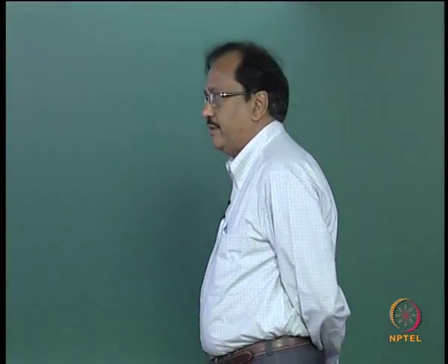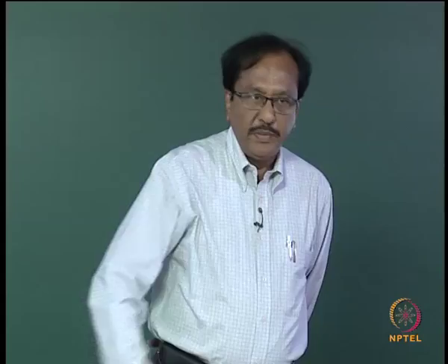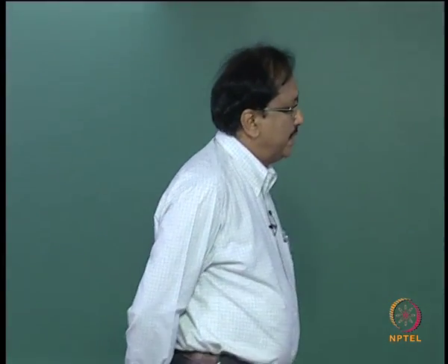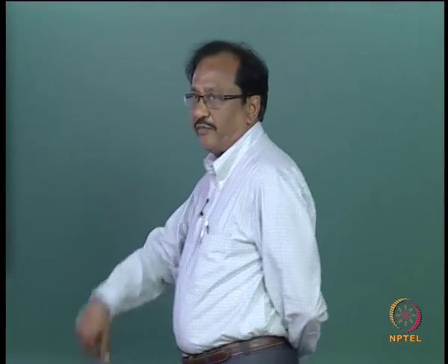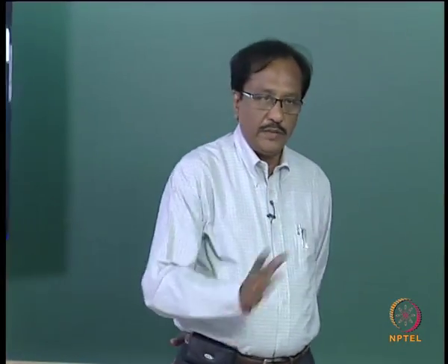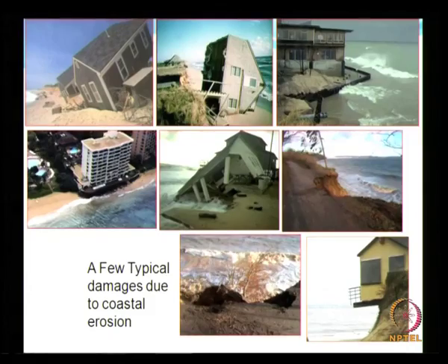So many times this erosion can be some kind of short term, only for some time, and it can be either gradual or all of a sudden. But one thing you should remember is, whenever you plan to have a structure in the coastal area, you have to look for this kind of effects on the adjoining shoreline. Now when you put a structure, what happens on the adjoining shoreline? So now we see the problem.